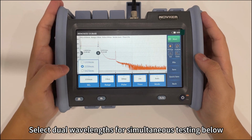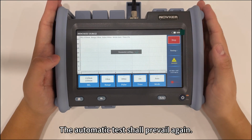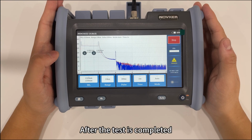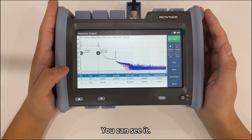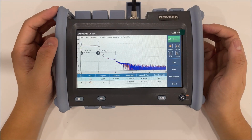Select dual wavelengths for simultaneous testing below. The automatic test shall prevail again. At this point, the device will first test with a wavelength of 1310 nanometers. After the test is completed, it tests at a wavelength of 1550 nanometers. You can see the actual range of the backlight fiber is about 2 kilometers.